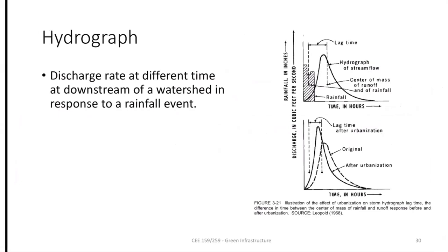Hydrograph, again, we go back to the main point that we discussed. The lag times are important. And even though that time I said the peak is the factor, as I said, peak is very hard to determine because it depends on how frequently we are taking samples. So practically, it's always the center of mass. If your rainfall distribution and the runoff is like a binomial curve, then the peak coincides with the center of mass. So that's why this is peak and this is center of mass.